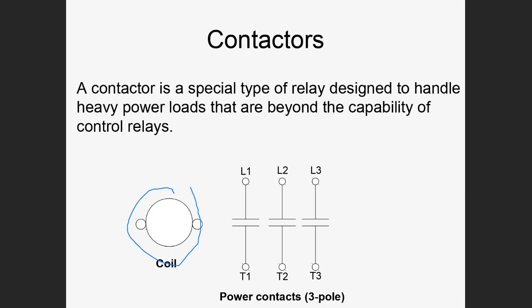So you can plug your TV set into 120 volts AC. But maybe you have a heavy-duty dryer or washer in your basement, and it connects to 240 volts AC. What's brought into your house is 240 volts, and they can split the phases down to two 120-volt phases, so you can use appliances that operate off 120.